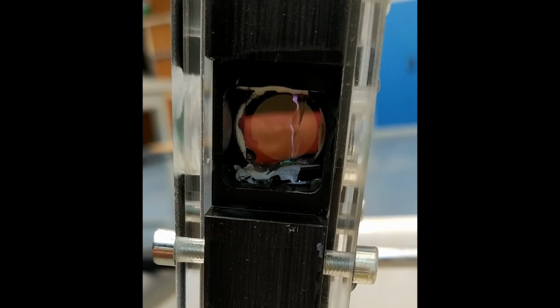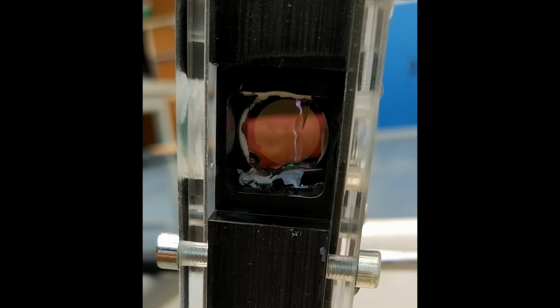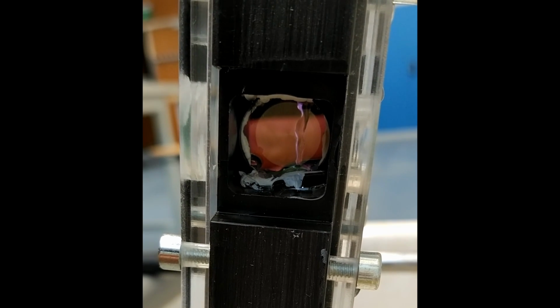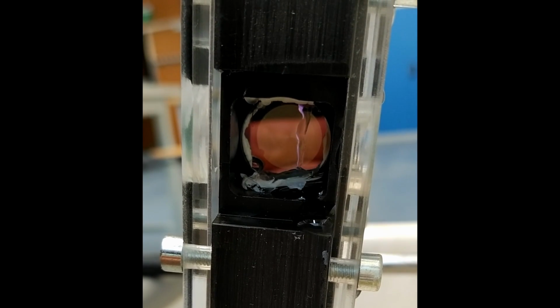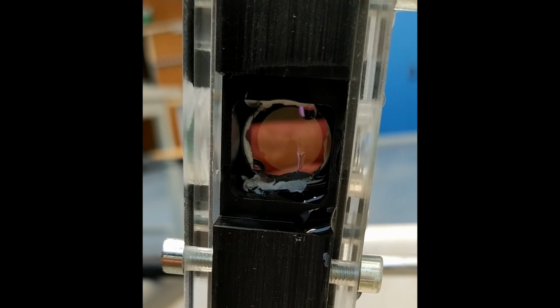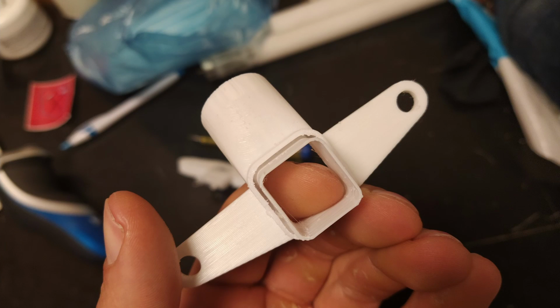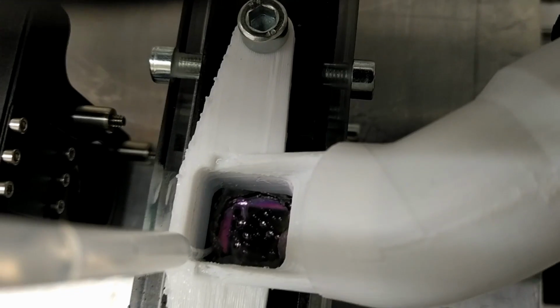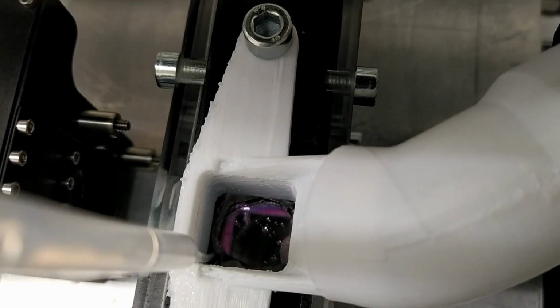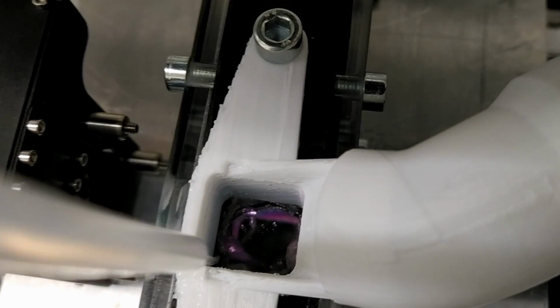The laser glass started leaking due to the PIV measurements at high flow rates. The water on top of the laser glass can distort the incoming laser light. That needs to be prevented. I 3D printed a nozzle to suck away the water on top of the glass with a vacuum cleaner, which worked nicely to circumvent the problem.